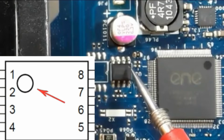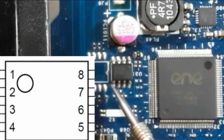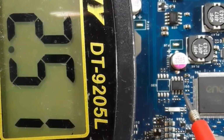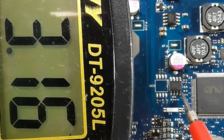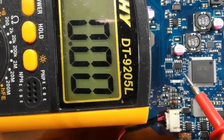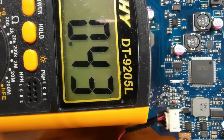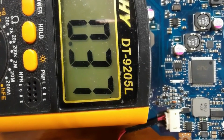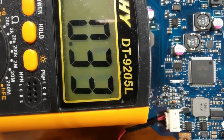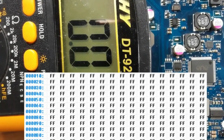We have this dot here, which means this is pin number 1, 2, 3, 4, 5, 6, 7 and 8. So let's check pin number 8. As you can see in the multimeter, we have 3.3 volt. So if you find 3.3 volt on pin number 8 of the BIOS, but the laptop still does not work, it means you should reprogram the BIOS. Because about 90% of the time the file or the firmware inside the BIOS is corrupted.